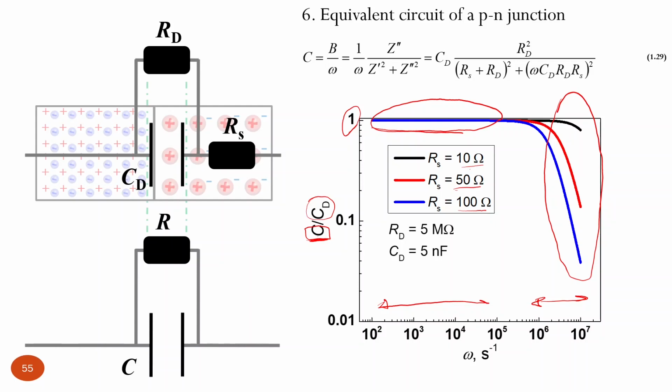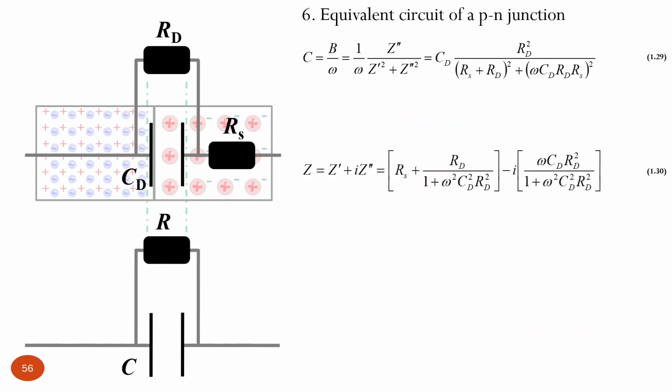But in this region where we don't have parasitic effects, we have the effect of series resistance, and that messes things up. So how can we deal with this? It actually has a very simple and straightforward solution. If this resistor is a problem for us, we can subtract it.